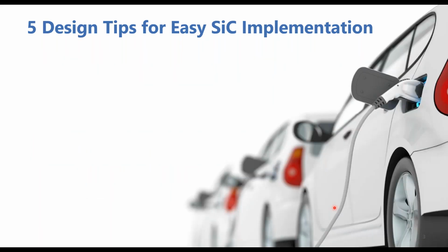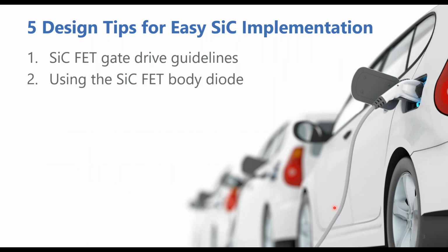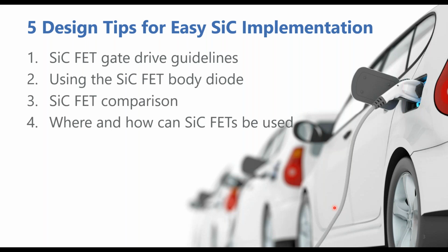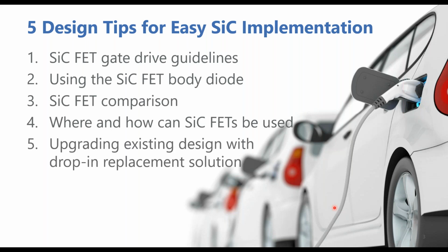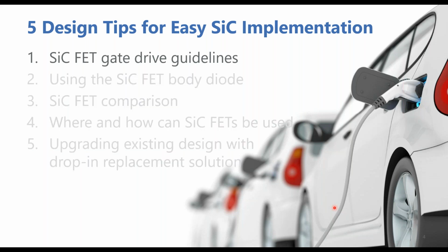So that leads us to the 5 design tips I would like to give you today. The first one is silicon carbide FET gate drive guidelines. Second is about using the silicon carbide FET body diode. And the third is silicon carbide FET technology comparisons. And after that, I would like to show a few cases where and how you can use silicon carbide FETs. And the fifth is what to do if you want to upgrade your existing design with a drop-in replacement solution. Okay, so first, let's look at the gate drive.